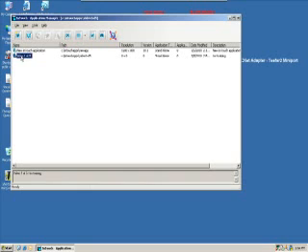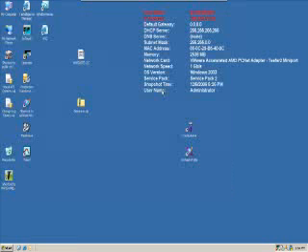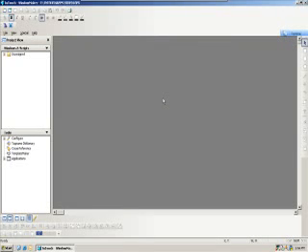So let's start the development environment called Window Maker. So here's our blank InTouch application. Now we can start from a lot of different angles with InTouch. We can start by creating tags, we can start by creating graphics and windows, lots of different ways of doing it. We're going to simply start by creating a new window.